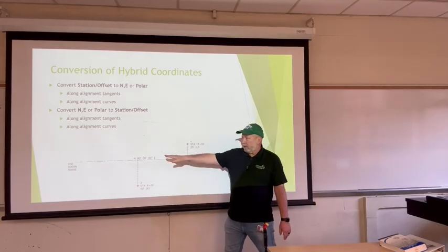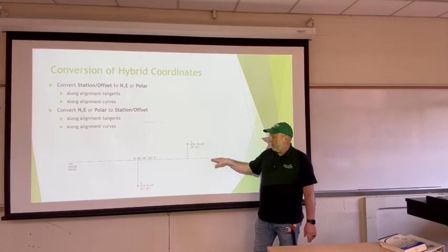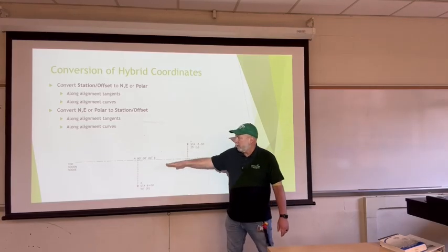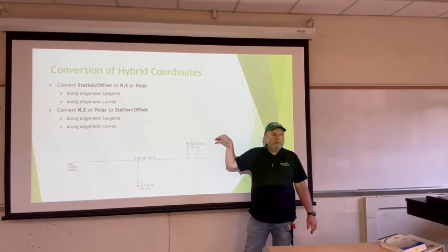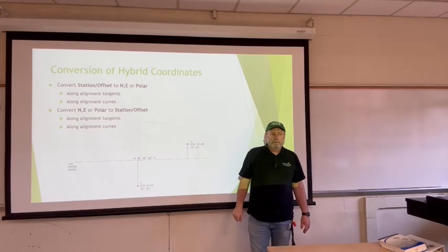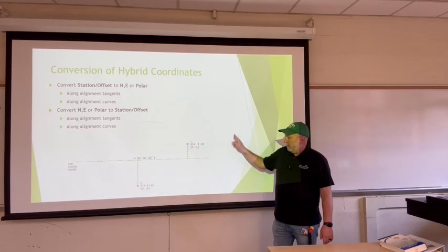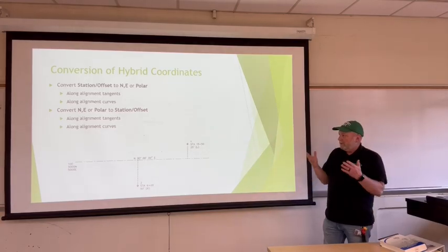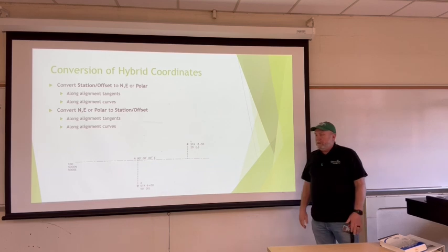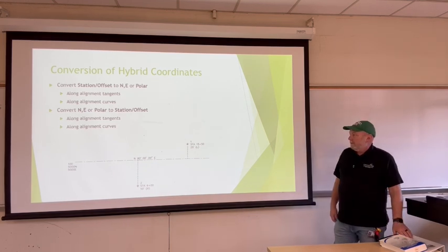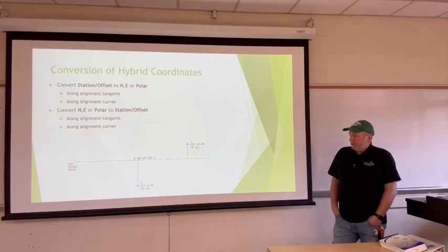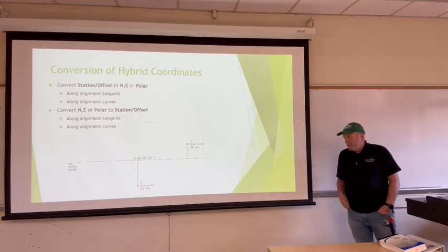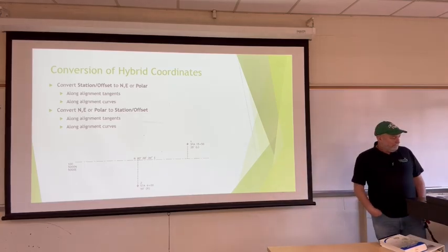We would actually occupy on that center line, backsight the other end of this tangent, and calculate how far up, how far over, and what angle we had to turn and the distance we had to go to actually set that point. And then likewise for the other one. So knowing the triangles is, I think, very important. And again, when you go take your fundamentals exam, knowing the math will keep that reinforced in your head. It will benefit you.